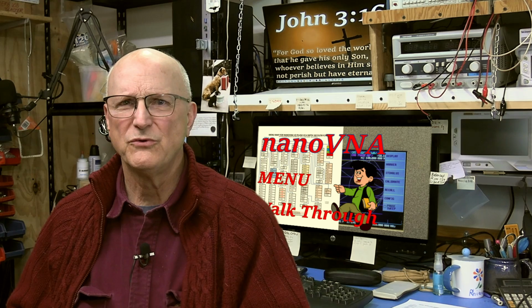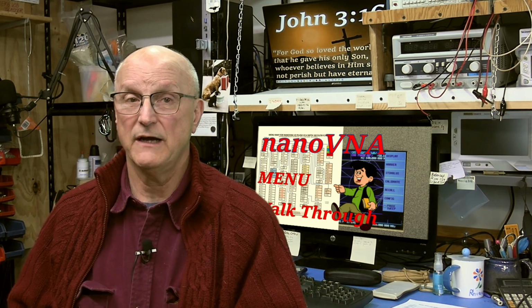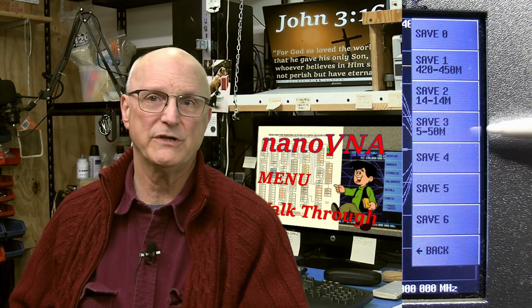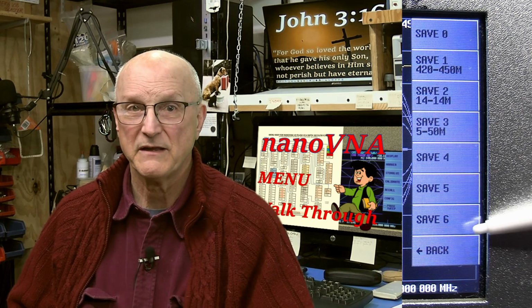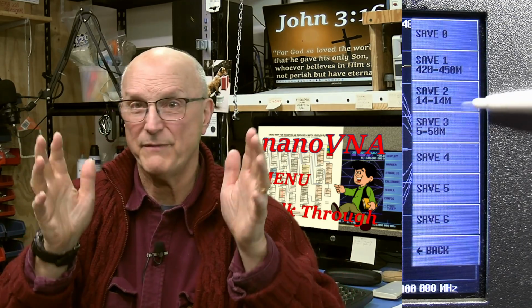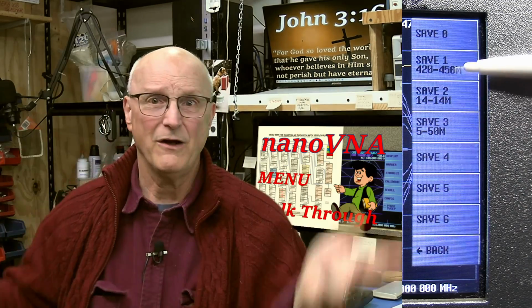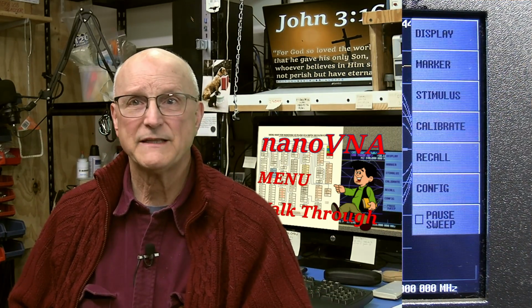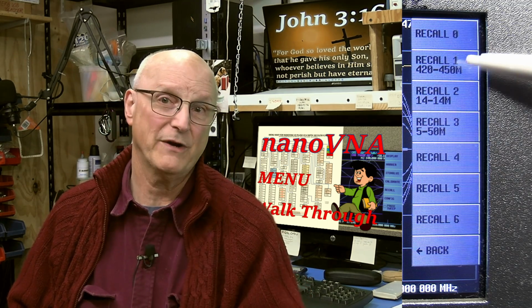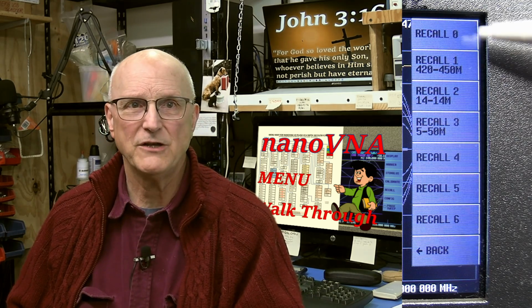One more really cool thing. At the end of the calibration process, you tap on the Done menu item. You will now have the opportunity to save the calibration data you just completed. But more than that, it saves the entire measurement setup, including trace definitions and scales and marker definitions, and a whole lot more. To come back to this same place, all you have to do is recall the specific configuration you saved. The recall option is available on the main menu.